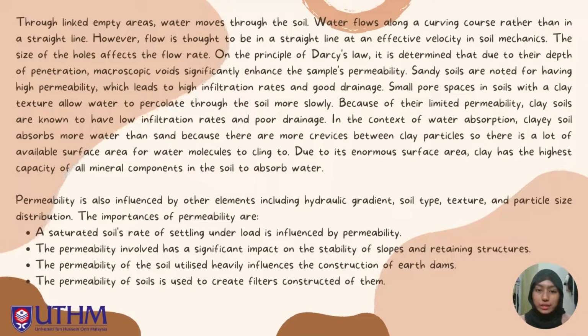For results and discussion, water moves through the soil by filling empty areas. Water flows along a curving course rather than in a straight line. However, flow is thought to be in a straight line at an effective velocity in soil mechanics. The size of the holes affects the flow rate. On the principle of Darcy's law, it is determined that due to their depth of penetration, microscopic voids significantly enhance the sample's permeability.